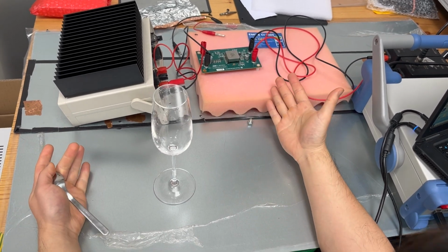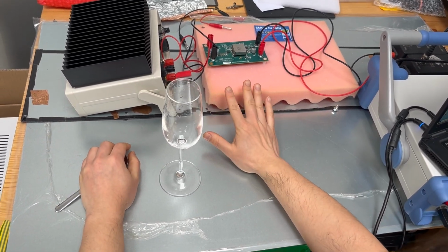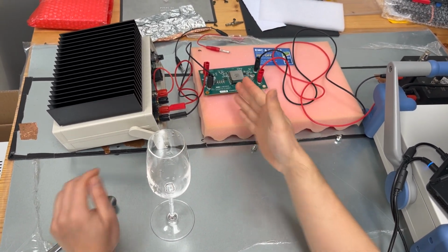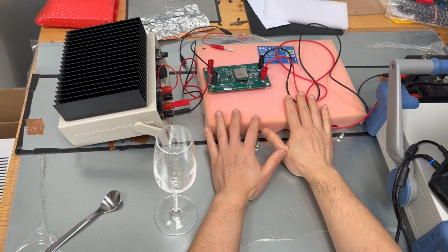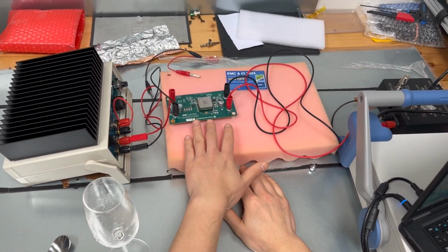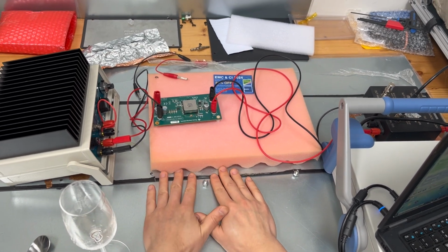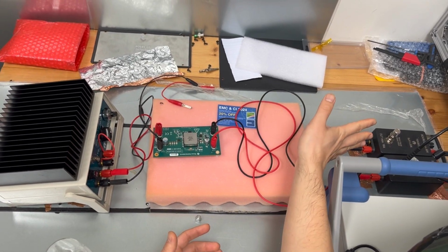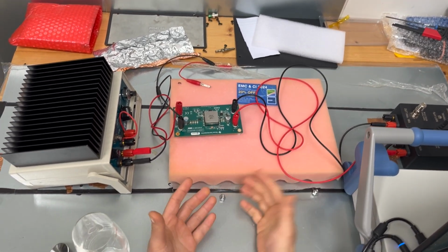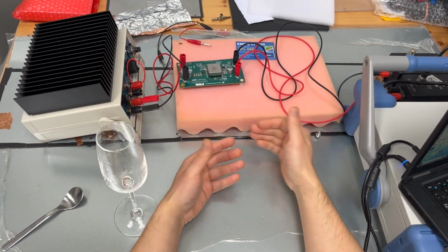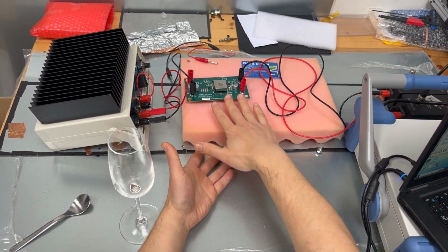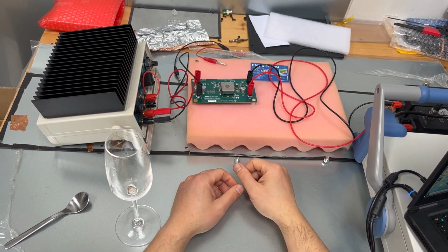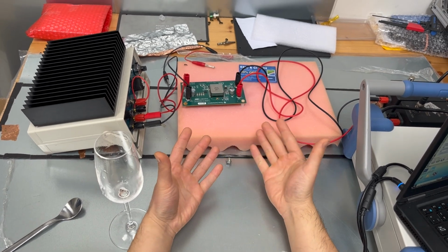First is the resonance structure. In this case, the resonance structure is formed by the DUT, which is the PCB. The structure, right? We've got long cables. We've got some parasitic capacitance between the PCB and the test ground plane. And also, we've got the LISN, and the LISNs are basically just some L and C components. So as you can see, we have the cable wires, which you can treat as inductance. This is capacitance. So the whole circuit is an LC circuit. So naturally, we have an LC tank circuit.